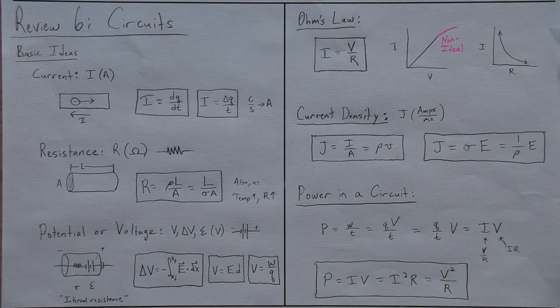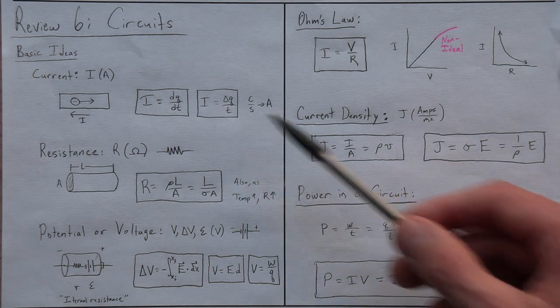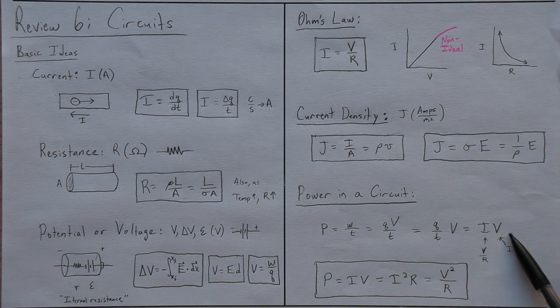So what I'm going to do here is derive the expression for the power in a wire or an electrical circuit by realizing from this formula, if I solve for work, I get QV. So I'll put QV in for work right here. And then I'm going to separate the Q and the time together. And Q over T is the current, as we saw over here. And so what I have is current times voltage. That derivation is in the curriculum, by the way. You have to be able to do that.